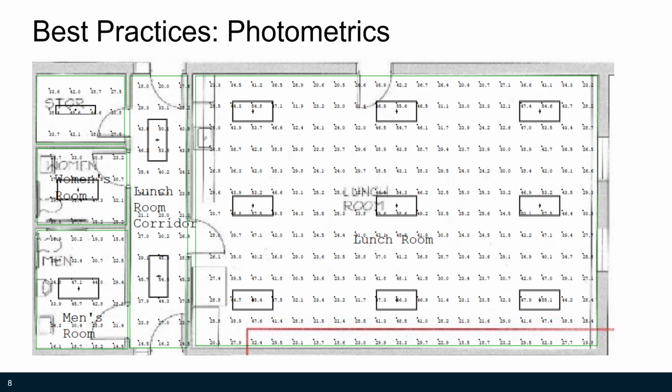Additionally, UFCs require the completion of photometric analysis to confirm light levels are consistent with UFC requirements. Photometrics are often offered as a free service by manufacturers, distributors, and lighting sales representatives. Contractors can readily access this no-cost resource, and design teams typically employ staff not only capable of performing this task, but that regularly utilize photometric analysis as a part of their typical design process.